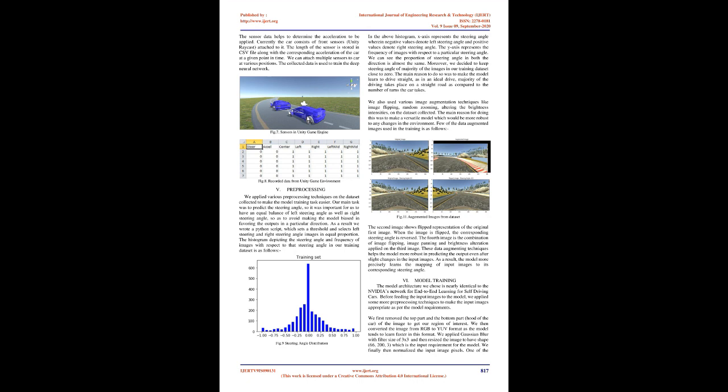4. Dataset collection. The main part of creating a more precise neural network model begins with collecting relevant data. Our Udacity simulator has two modes, one is the training mode and the other is the evaluation mode. The dataset collection takes place in the training mode. There are 3 cameras mounted in front of our car in Unity. The locations of these cameras are front left, front center and front right to more precisely capture the surrounding environment.